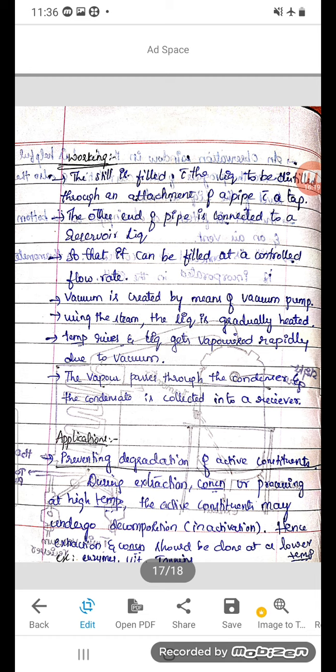Drying at atmospheric pressure yields a dense compact residue which is not desirable. By this method you get a porous material. Under reduced pressure it produces a light porous mass which can readily be passed through a sieve to form a granular powder. So the physical form can also be changed, and you can get a porous solid mass.